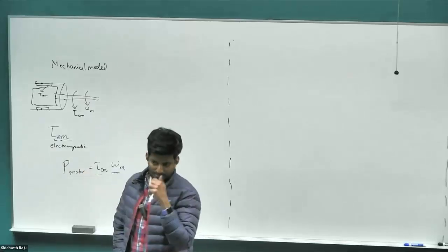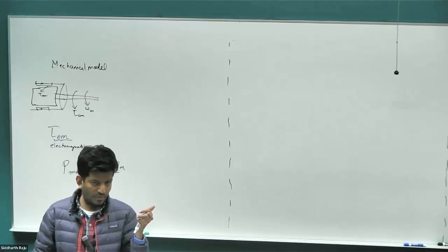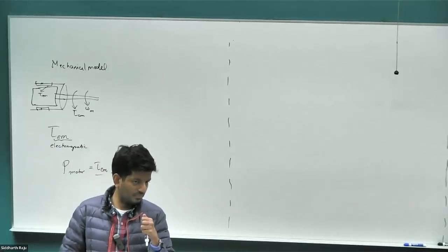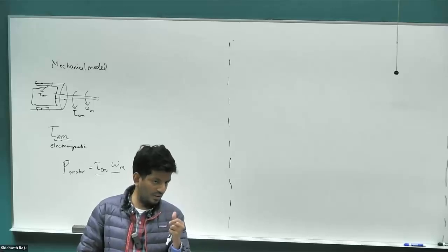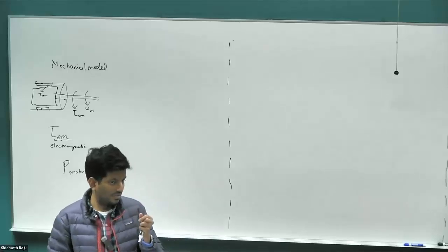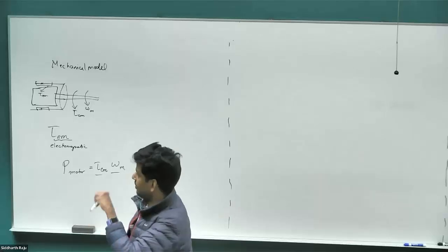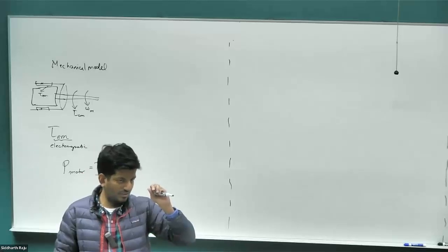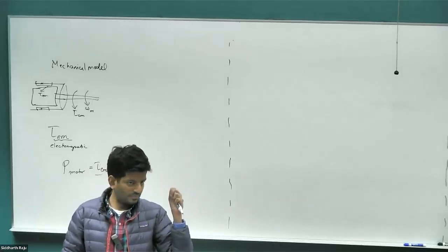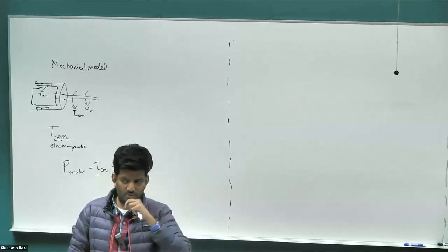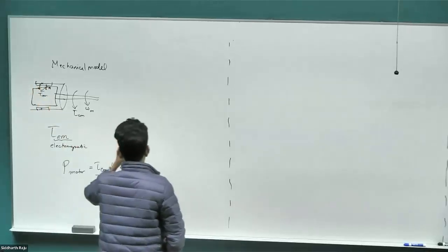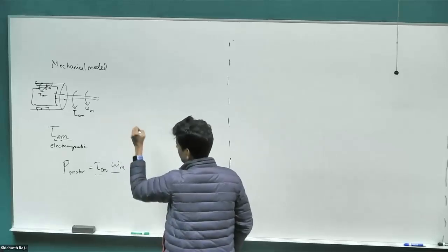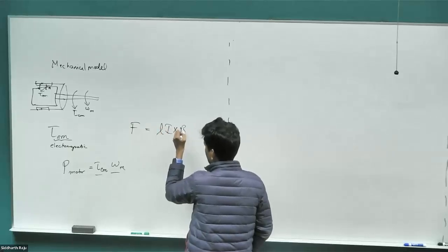How do I reverse this torque? Let's say EV motors are not using DC motors, but let's say it's a DC motor. We cannot change the commutator anyway. It's a physical element, like the contact, the brushes. We can't change anything mechanical. This is why we have put the motor already in the car and the motor is running. You want to change the torque polarity. What was torque directly proportional to in our derivation? What was force proportional to from the Lorentz force equation? Current. We cannot change the B field either. Once we put the magnets, the B field is fixed. There is going to be armature reaction, which we will not worry about, but the B field from the magnet is not going to change.